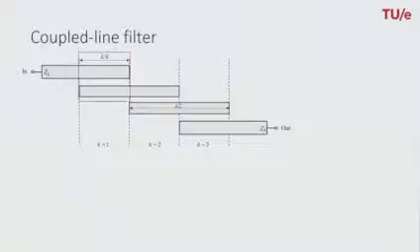And in this way we create, in fact, three coupling pairs, as you can see in the picture, varying from KS1 to KS3 in this case. But of course we can have many more sections. The coupled pair resonators provide even and odd modes, so even and odd modes can propagate along these coupled pairs. And associated with even and odd modes, we have even and odd mode characteristic impedances.